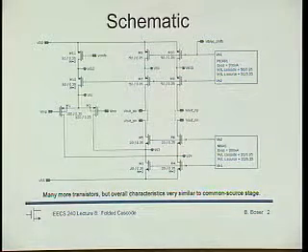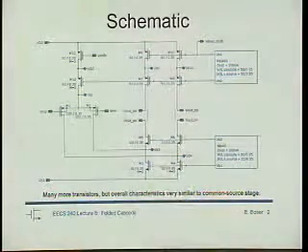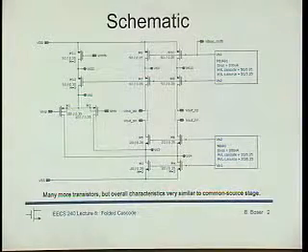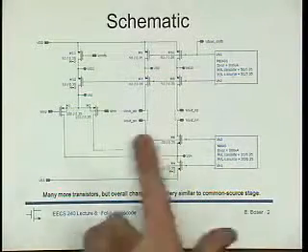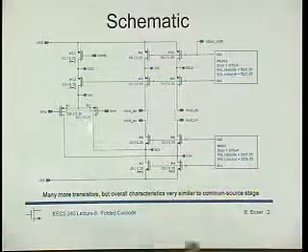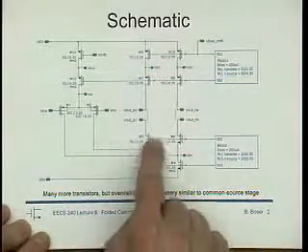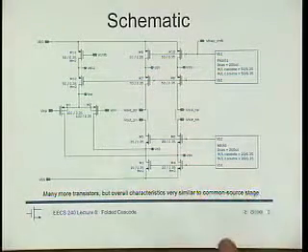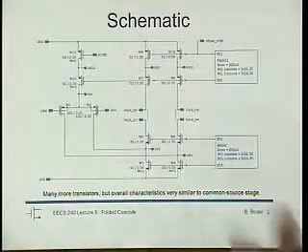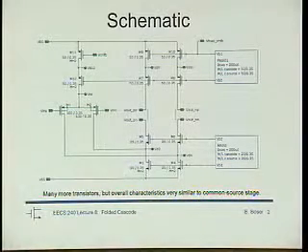FT, right? So we're going to get an additional pole in this circuit, from this circuit, that is the FT of these cascodes. Maybe a little bit lower than the FT because there is additional load hanging here in addition to the CGS. But that's what comes here. So it's really true what I'm saying.